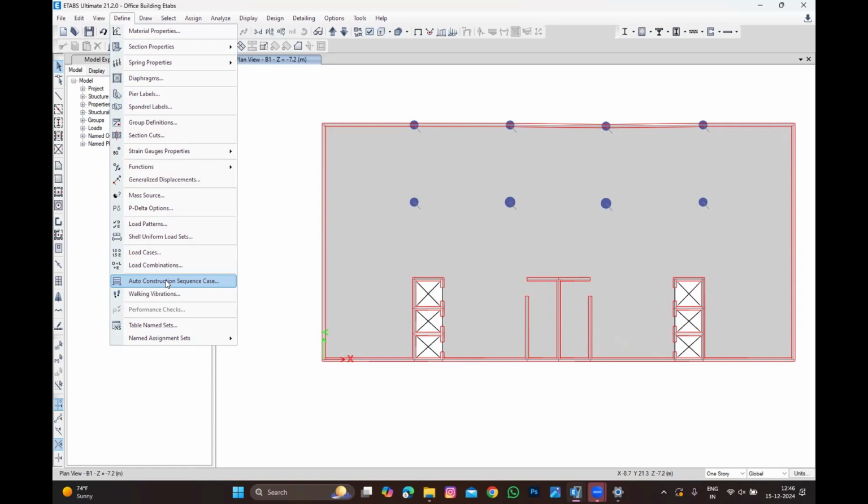Reinforcement is same. You're not going to reduce the reinforcement. Section sizes are the same. After 5 years, are you going to reduce the reinforcement? No. Still the same reinforcement, still the same section size, still the same effective depth, which is not going to change. Only the material reduction factor is going to play around to increase your deflection further. Same as the human body: when you're standing after 50 years, you will bend because of deterioration. Your deflection is more, right?